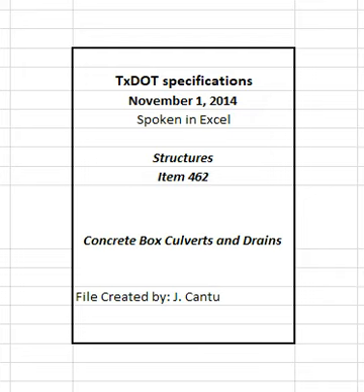2.4 Lifting holes. Provide no more than 4 lifting holes in each section for precast boxes. Lifting holes may be cast, cut into fresh concrete after form removal, or drilled. Provide lifting holes large enough for adequate lifting devices based on the size and weight of the box section. Use lifting holes no larger than 3 inches in diameter. Cut no more than 5 inches in any direction of reinforcement per layer for lifting holes.